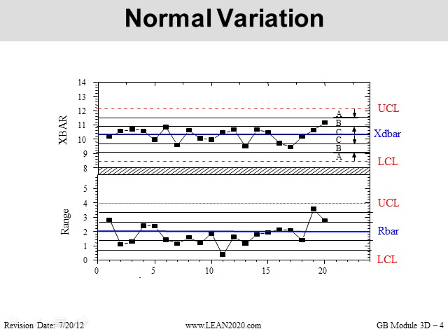So here's a particular chart. It's an X bar and R chart. So we have a top portion and a bottom portion. The top portion looks like it's relatively stable. I don't see any patterns or anything that would cause any alarm. Same thing with the bottom. So this is normal variation. This would be considered a stable process.